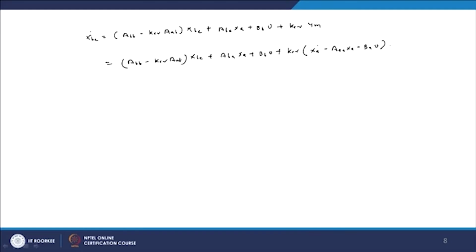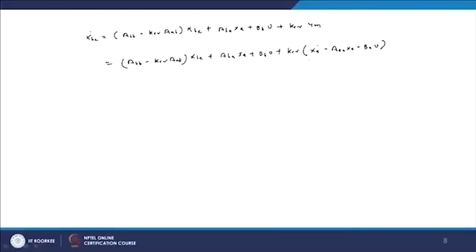So, now these equations we have solved. Now, we have to see the point. Here we have got the state equation for the minimum order observer XB dot, but now XA dot is there. That is, y equals XA, and in the state equation we get XA dot, which means noise will be amplified and that creates problems. Therefore, we have to remove the effect of XA dot, that means in our equation there should not be terms like XA dot. So, in order to handle this, we write the above equation as